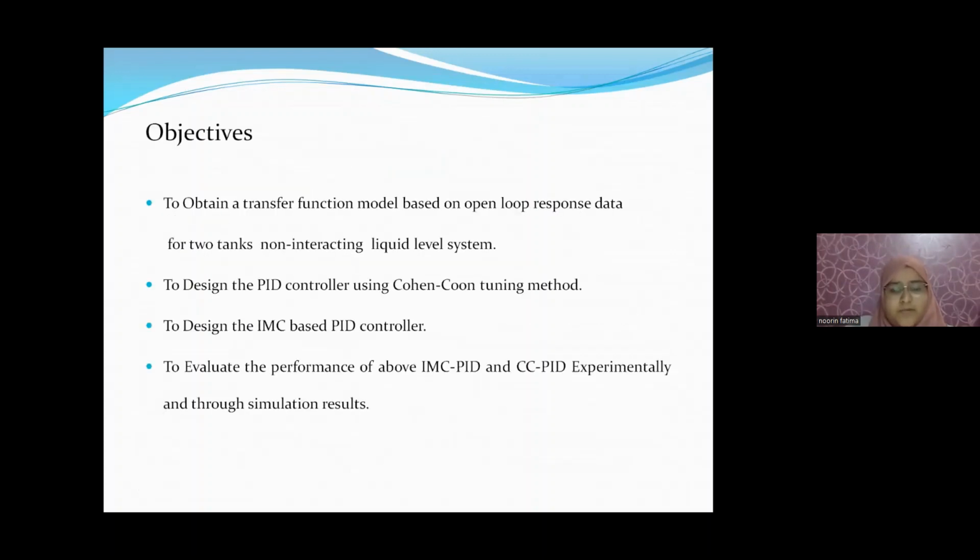Then my objectives: to obtain a transfer function model based on open loop response data for a two-tank non-interacting liquid level system, to design the PID controllers using the Cohen-Coon tuning method, to design the IMC based PID controller, and to evaluate the performance of the above IMC PID and CC PID experimentally and through simulation.